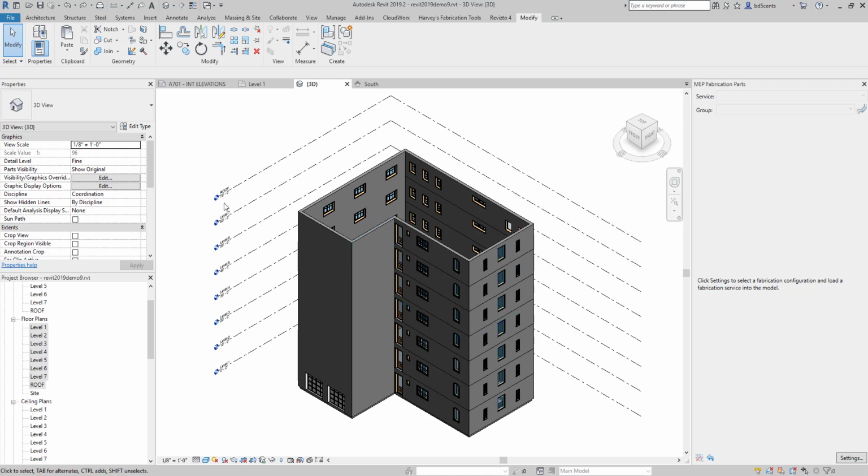Note that they don't really build walls 70 feet tall as a single wall, but you can model it that way. So what's important to understand with what I just said there is that just because it's modeled in Revit doesn't mean it can be built that way. So just bear that in mind, that when you're modeling things, try to, as a draftsperson, be as accurate to the real world conditions as possible, because if you start drawing things that are not accurate to real world conditions, you're going to catch a lot of flack from people that build, as well as from architects that don't want to see that, or engineers.